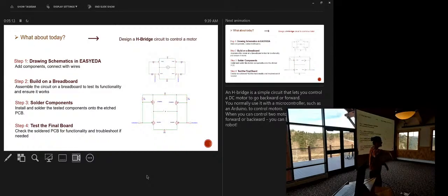Transistors are some simple components, you can use them. I bring them here to show you. You can use them, but if you want a very fast switch, if you use MOSFETs, it's better. And you saw many H-bridges have diodes to make the direction ones, but MOSFETs have inherent diodes inside them, so you don't need to use diodes for them.